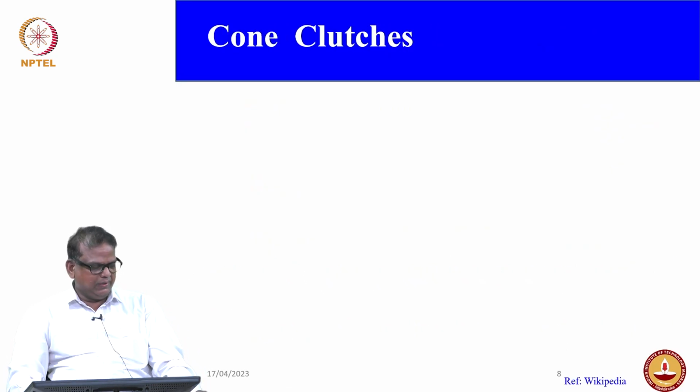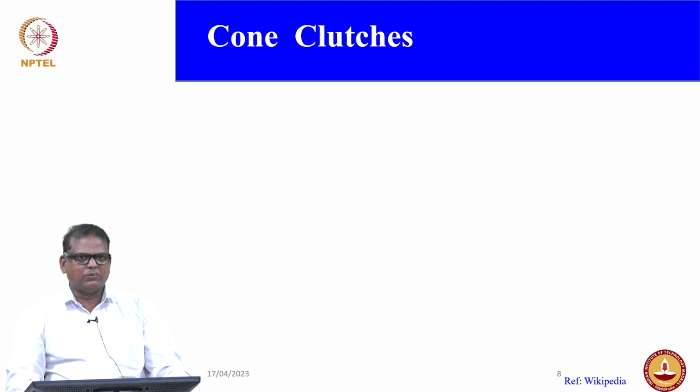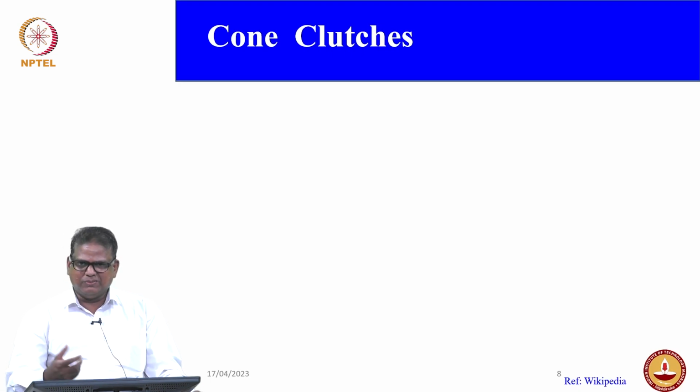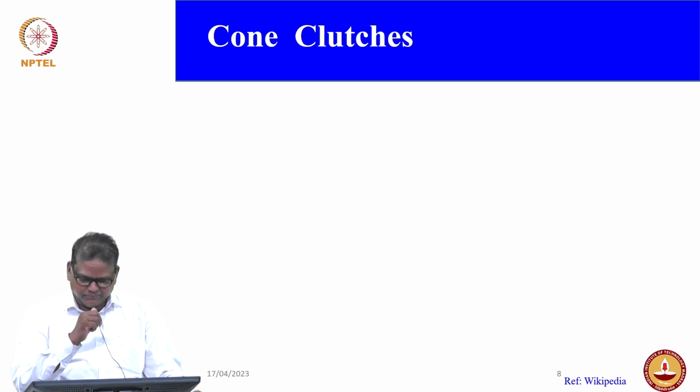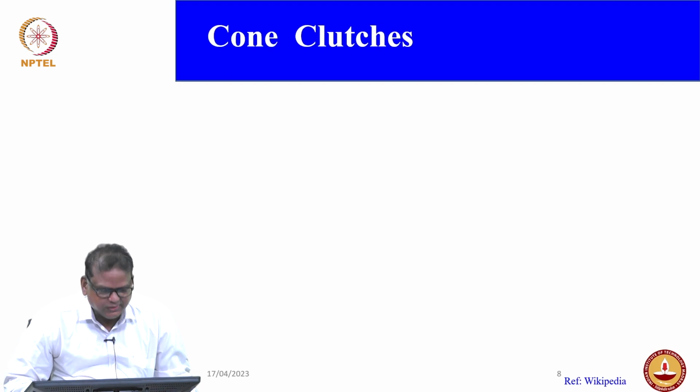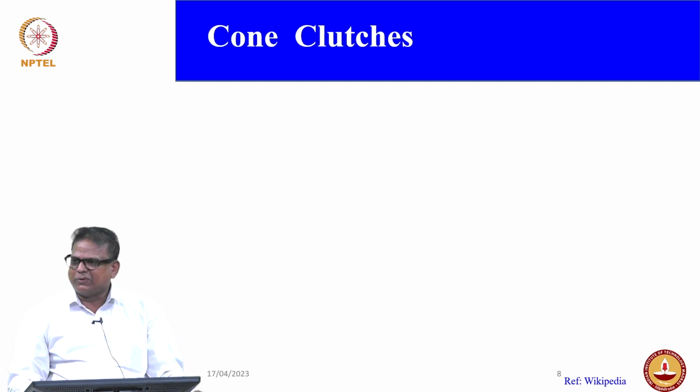Now, we will move on to the cone clutch, okay. There is one more type called a cone clutch. Have you ever seen the cone clutch first of all? If you had come to my office, I would have shown some synchromesh gears. Maybe I forgot to bring it here, but I will show it maybe in tomorrow's lecture. It is extensively used for transmission, that is one specific application of the cone clutch. Are you aware of any application for the cone clutch? How about a moped? In a moped they have a cone clutch arrangement.